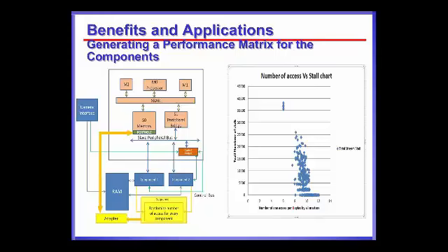So it has no bearing on this M0 processor shown as master 0, fetching those instructions and putting them into the memory, which is shown as S0, because these components are triggered once the entire hex code, or the instruction code, is available in the S0 memory. So execution of the components is dependent on execution of the main processor.